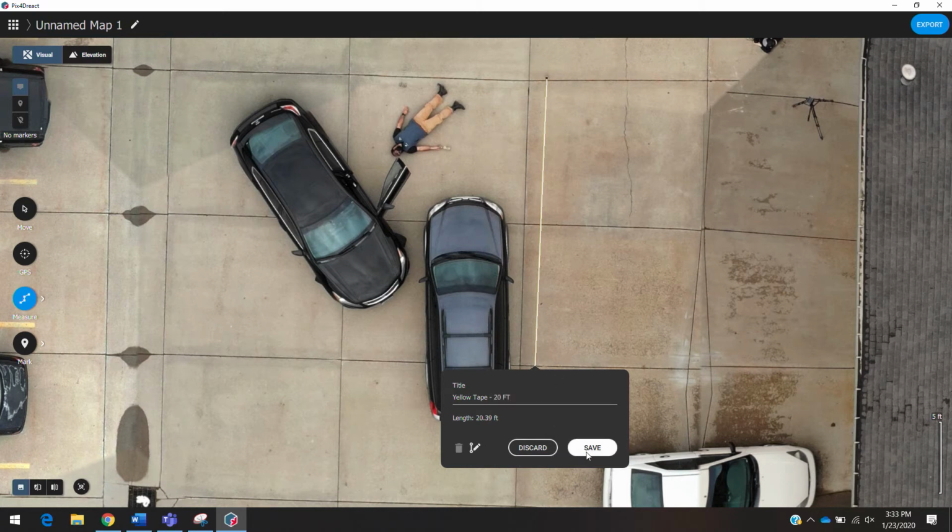And we're showing that to you just to demonstrate the power of the software plus the GPS on the drone, you're going to get pretty accurate results. Sure, sometimes it's not going to be great. Sometimes it may be a couple inches off. But for the majority of use cases, this is going to be pretty tight. And you can always put a 20-foot metal tape down or a 50-foot metal tape down in the scene, something we call a reference measurement protocol, to just demonstrate the accuracy of the measurements.